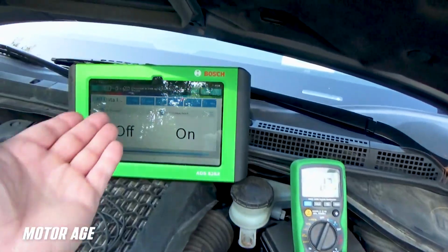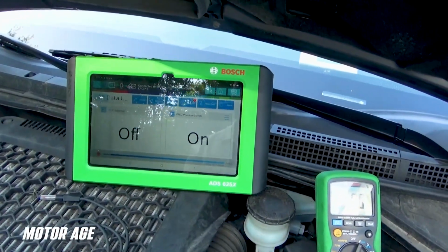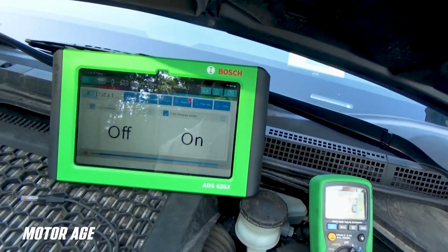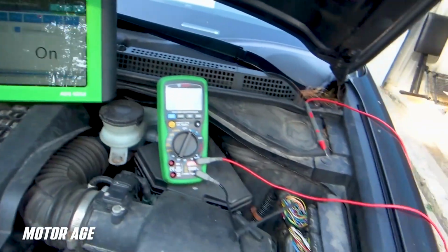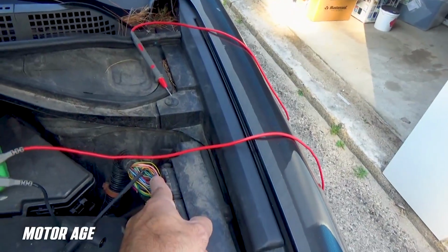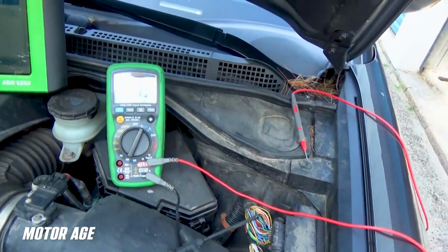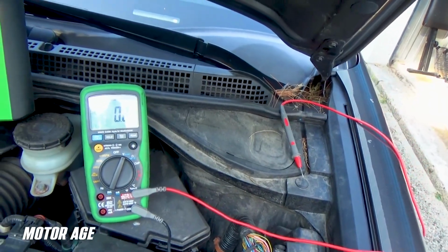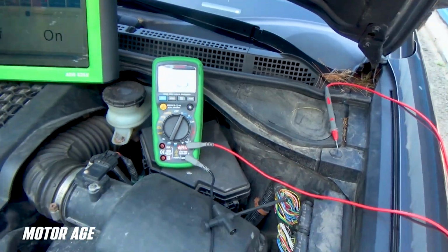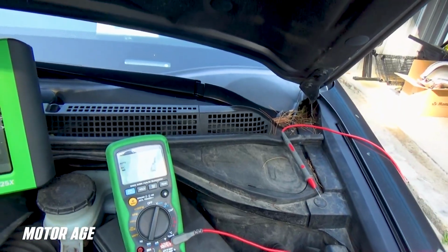So again, using the easy-to-access wiring diagrams and component locator from our information system powered by Motor, I was able to easily locate the pertinent connector and terminal and related wire color for our VTEC pressure feedback switch. Leveraging our Bosch MMD540H hybrid multimeter, we're simply going to check available voltage at that sensor signal terminal.